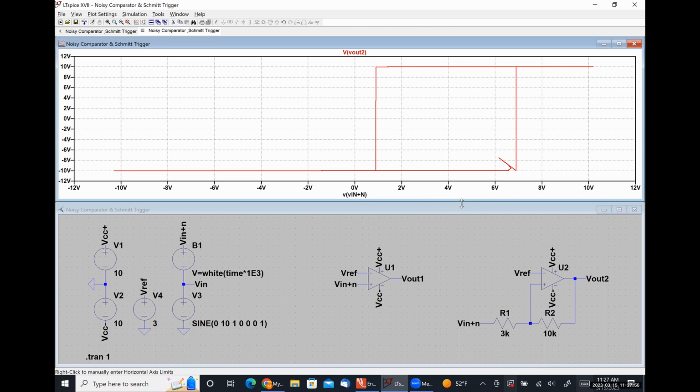And we get this funny looking graph. This is what would commonly be called a hysteresis loop, and the reason we have a graph like this is because our Schmitt trigger has latching. Effectively, we look at this graph from left to right. As our input voltage increases from -10 volts, we don't trigger high until we get here, and then we're at high.